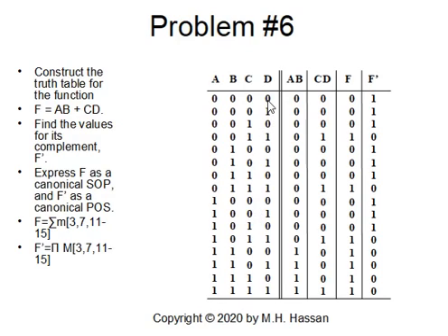Building the truth table, we start with the least significant bit D, and we toggle 0, 1, 0, 1 till the end. We have 16 rows here, and for the next column 0, 0, 1, 1, and so on. Then we calculate A and B, which is an AND operation, and C and D. Then take F, AB or CD. As you can see, we generate F as 1 here because 0 or 1 is 1, and we generate 1s here. So F will be the sum of the minterms 3, 7, and 11 to 15.